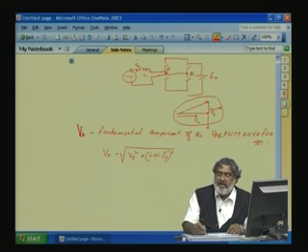So, VAB: from the previous sine triangle analysis that we did two days before, for one leg the maximum amplitude of VA will be equal to VDC by 2, or E0 by 2. So, when we subtract A and B, the maximum fundamental value of VAB will be equal to E0. That is the maximum voltage VR we can get.